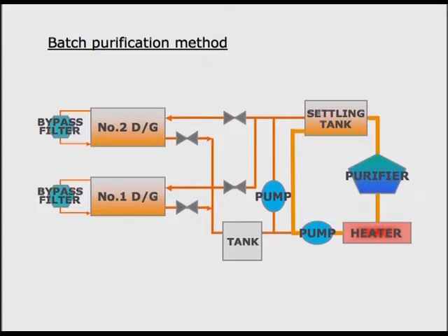Set the cleaning time in such a way that the lube oil of the settling tank flows to the purifier 20 times or more. Regularly carry out the cleaning of both the sump tank and overflow tank.